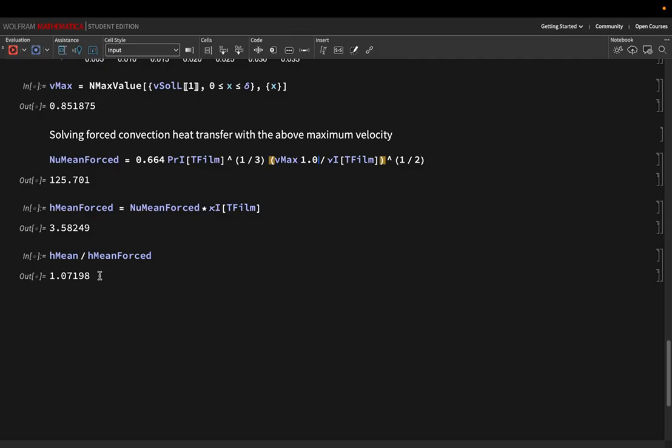So what is happening here? I'm getting the heat transfer coefficient to be higher in free convection than when I force it under similar conditions of wall temperature and so on. This is happening essentially because of the buoyancy force that is there in free convection. Maybe once turbulence is explained, it will be a little clearer. But even under laminar scenarios, because of this buoyancy term inside our governing equations, it enhances our heat transfer higher than it would be in a pure forced convection case.